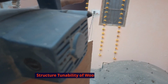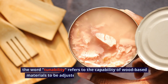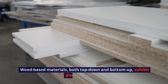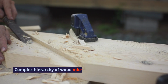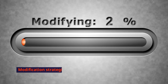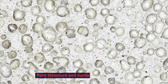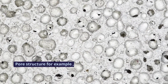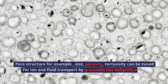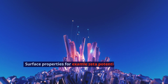Structure tunability of wood-based materials. The word tunability refers to the capability of wood-based materials to be adjusted or modified in various aspects. Wood-based materials, both top-down and bottom-up, exhibit diverse tunability. Complex hierarchy of wood microstructure and versatile chemistry of wood components enable tunability. Modification strategies include physical, chemical, or combined processes for tunability. Pore structure and surface properties tuning. Pore structure, for example, size, porosity, tortuosity, can be tuned for ion and fluid transport by processes like delignification, densification, stretching, or hole punching. Surface properties, for example, zeta potential, wettability.